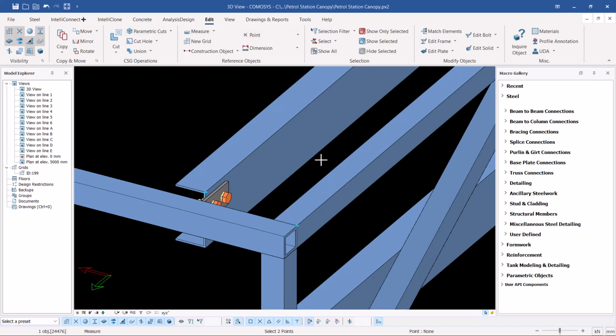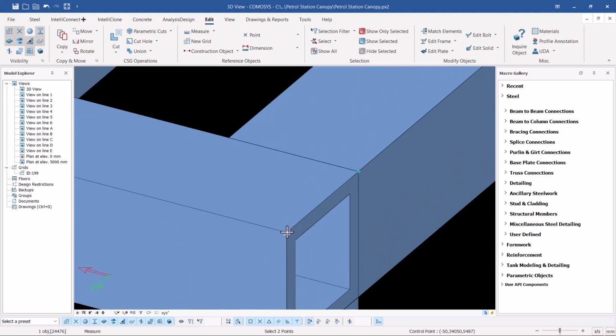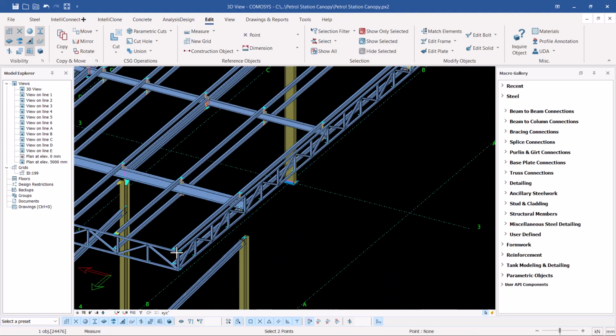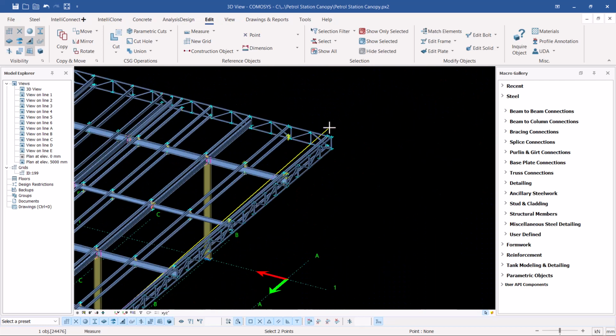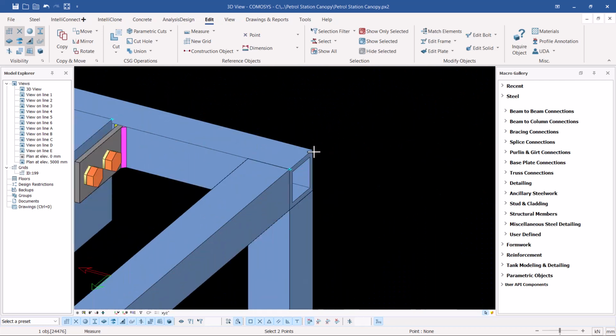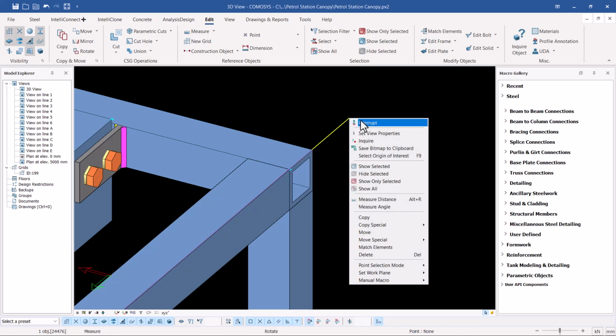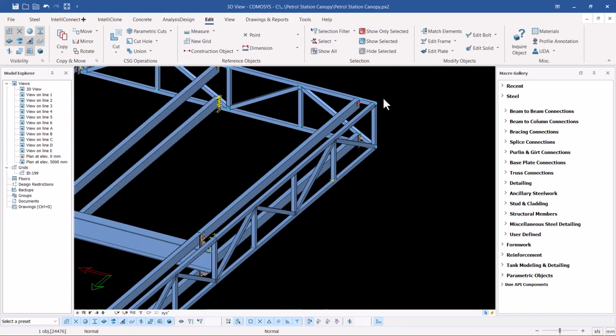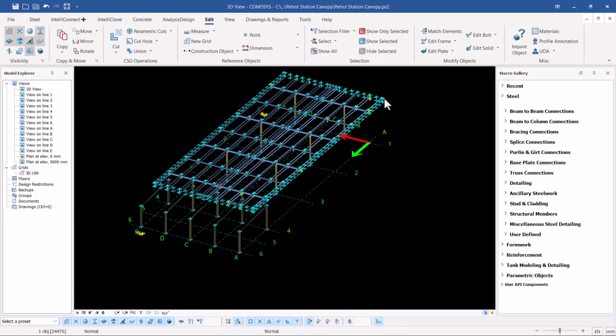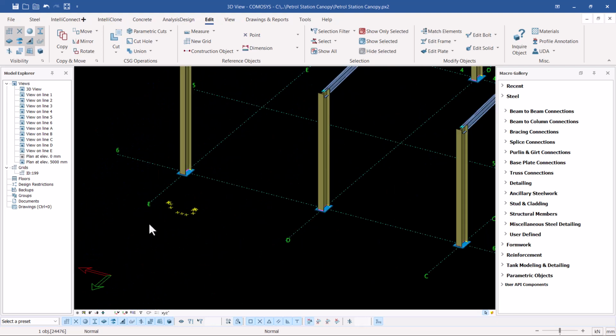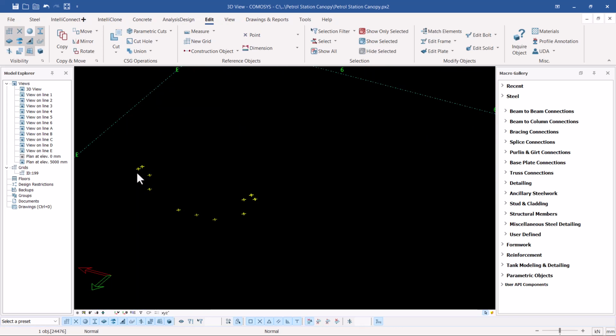So let's come to measure, and I want to start getting the full length here from the edge right there all the way to the far end here. So if I click on that end or just mouse over there, you'll be able to see I have 38.1 or 38,100 millimeter. Now I have some points already created here that will help me in creating a valley gutter profile.